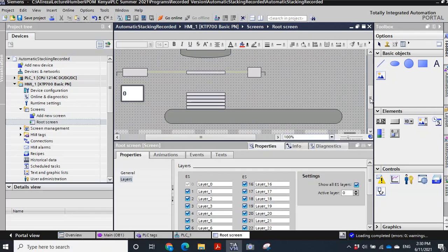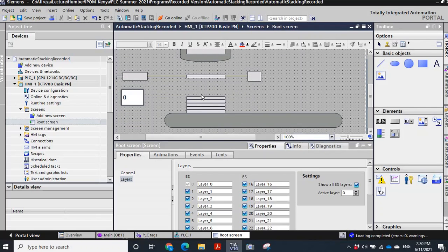So yeah, I think that everything is ready, and we don't have any start and stop in the HMI. The start and stop is by the switch. There's one reason that it might be better to have that as a local start and stop instead of having it in the HMI in the central control room, because these are moving elements, particles, and maybe it's better that there is an operator close to it every time to decide whether to start or to stop.